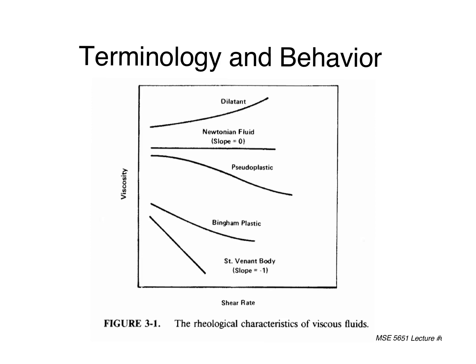And so we produce this blend, and we have different ways of thinking about the viscosity. And first off, there's one thing that you should know about, which is zero point of shear. What does that mean? It's a fancy word for saying we take these curves of viscosity versus shear rate and extrapolate them back to zero shear rate. And this is where you get these numbers, where you have this extrapolated viscosity value if the shear rate was zero, which is crap because it doesn't make sense, but it is a common way of referring to how these things behave.